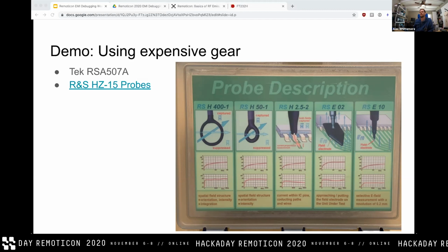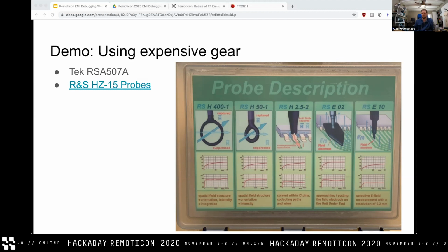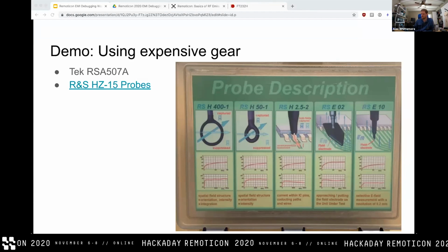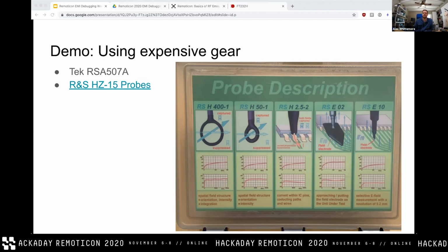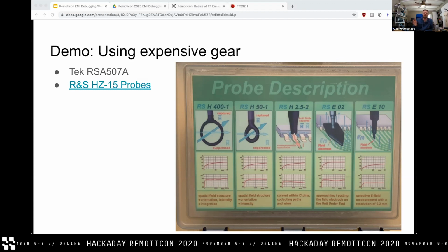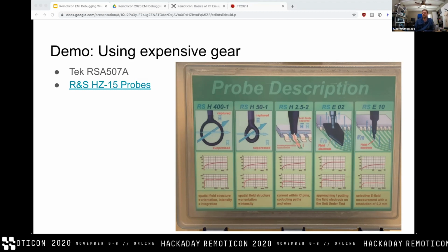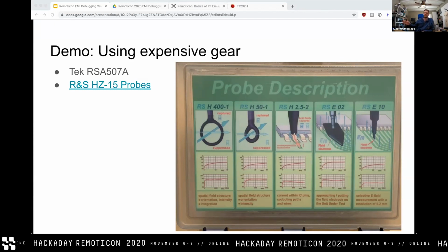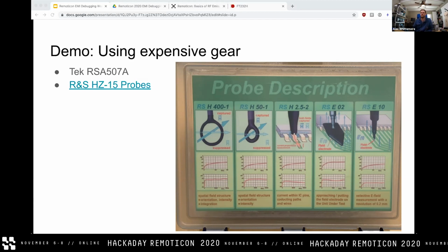As far as the RSA, I told you guys about swept spectrum analysis, where you look at one point and then move to the next in frequency and then move to the next in frequency and do that in a sweep. We can demo that with SDRs a little bit later, but the alternative to that, that's basically only possible with modern instruments and tools, is real-time spectrum analysis, where effectively you take a time series sample of a chunk of spectrum and then analyze it all at once, do an FFT on that time series data, and that gives you a frequency spectrogram of what's going on in the RF at that moment in time in that whole bandwidth. So SDRs do exactly this.